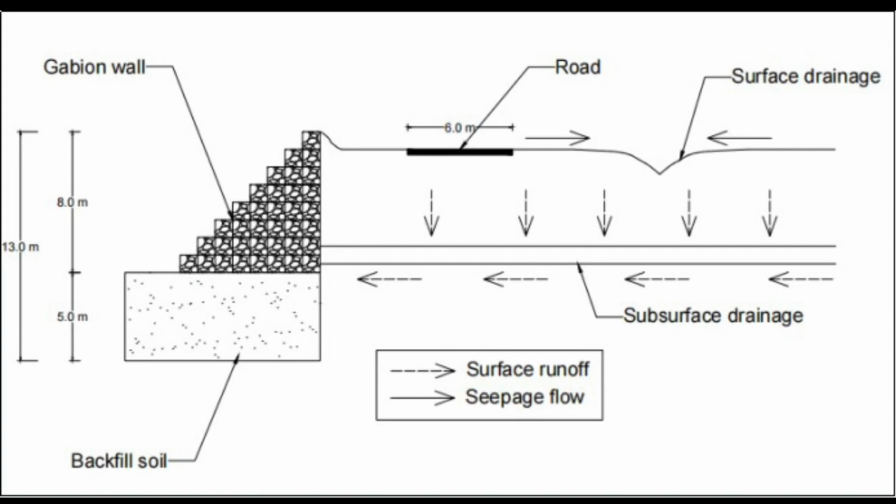In order to collect the groundwater, the casing pipes must either have their section that traverses the aquifer perforated or the pipe must have its entire length perforated, because a rigid pipe cannot accommodate the landslide movement that is occurring in an area without separating at the joints. Rigid pipes should not be used in an unstable area or in an area where there has been a landslide.